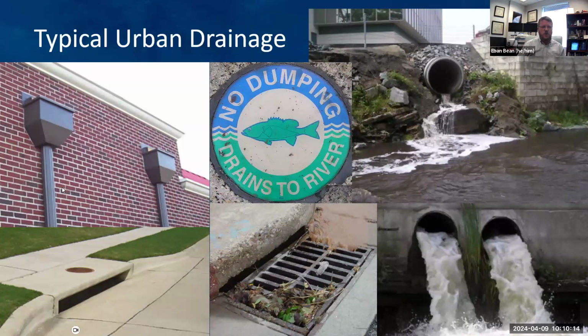landscape. I just want to point out before I move on that, if we look at the connectivity here, we have the rooftop that goes to the scuppers, the drains, then they go into maybe the street that goes into the storm drains here. And then oftentimes those will go into stormwater pipes that go to the nearest water body. And so that's basically trying to effectively get that offsite as quickly as possible.